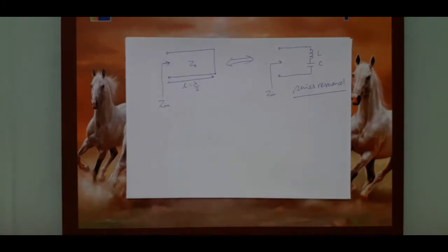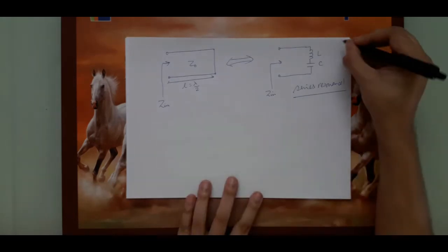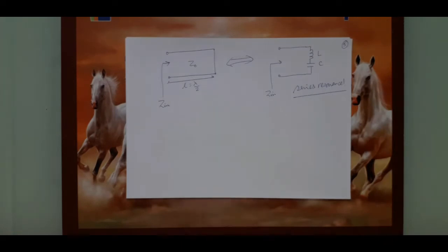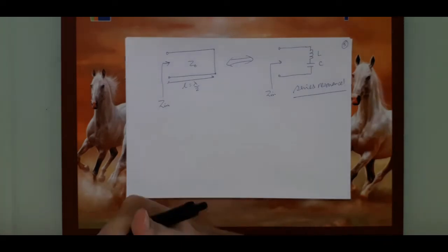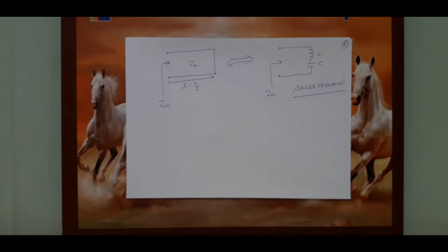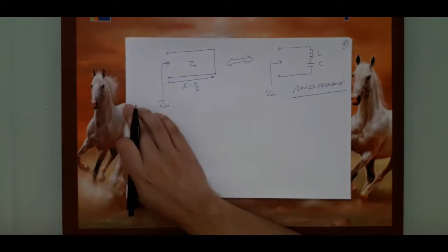So, what we have seen so far, we saw two applications of transmission lines. The first was where we are able to realize an actual function of an inductor or a capacitor using a transmission line that is short circuited and whose length is also thought of in an intelligent manner. That is, its length should be below lambda by 4.